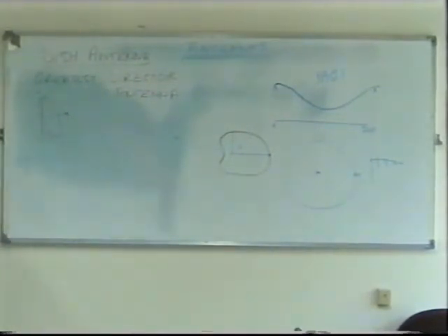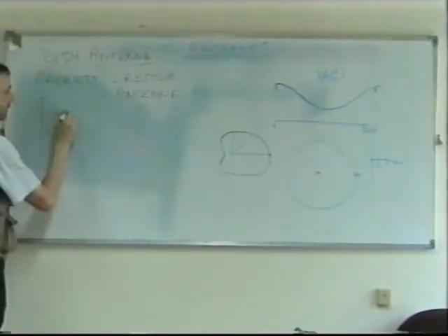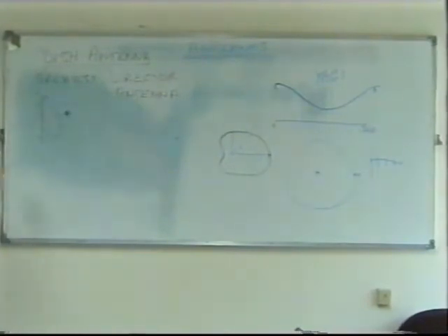The actual antenna in our dish antenna system, in a dish array, the actual radiator itself is a little thing here, a little dipole in fact, a tiny little thing there. And depending on the type of system you have, whether you're using this for, say, receiving TV signals or for a microwave link, whatever you're using, essentially you have a little radiator here. And that radiator radiates energy towards the dish.